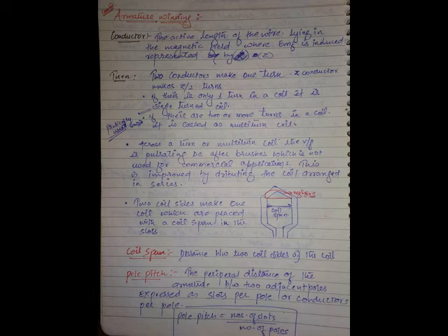To make you understand this data, there are 30 coils, 60 coil sides. If you do single layer winding, how many slot armature do you require? 60 slots, because each coil side is placed in one slot, so you require a 60 slot armature.